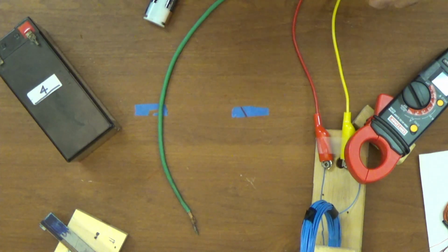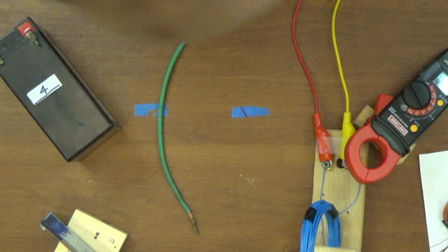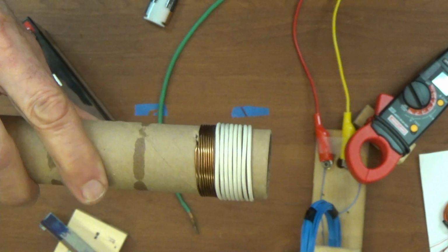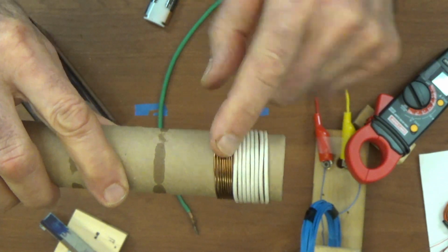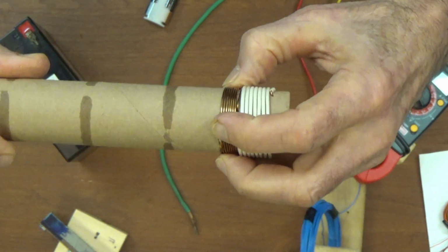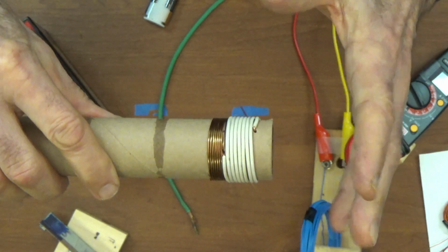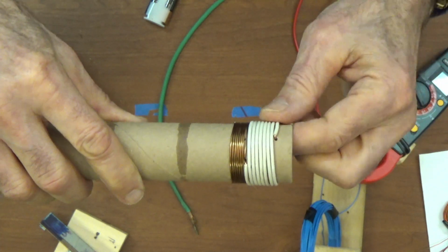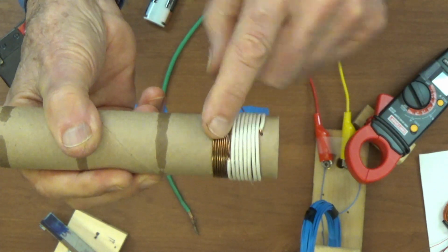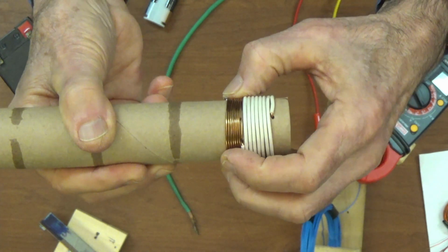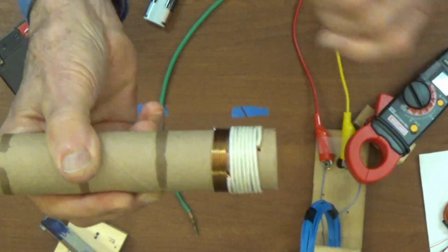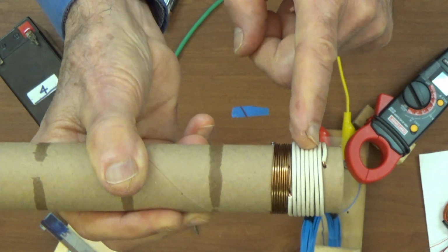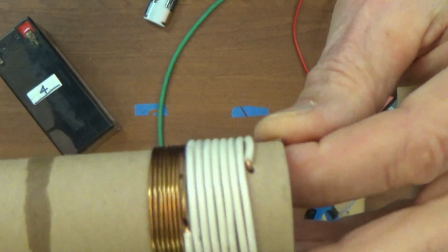Why do we use magnet wire? Well, there's two reasons. One is magnet wire has insulation. Did I say magnet wire is not magnetic? It's not magnetic. We call it magnet wire because we produce electromagnets. It's got very thin insulation. It's heat resistant. But because it has thin insulation, it takes up half the space of wire that has the same amount of metal in it. Let me show you here.